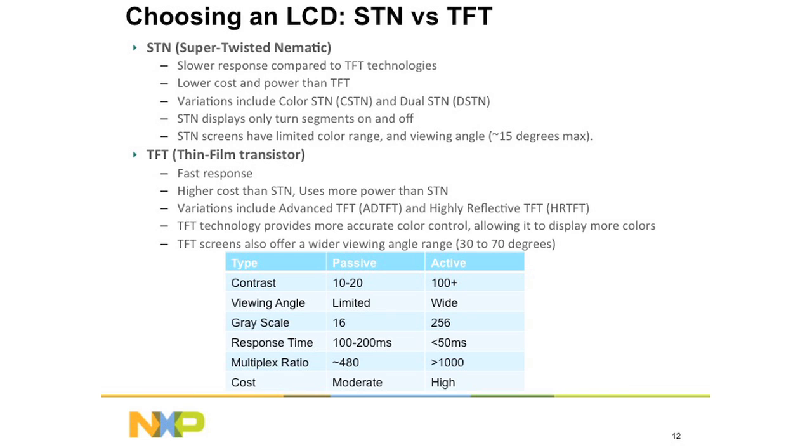The key limitation for a TFT is the cost. They still haven't been driven down to the cost that most applications can use. So STN, if you're looking for a low cost, and depends what kind of display you want, which is just, say, a digital, you're just displaying some numbers or keys or something, that's probably the way to go. But if you want high graphics like pictures, even just doing a still picture frame, for example, you would rather go with a TFT display.